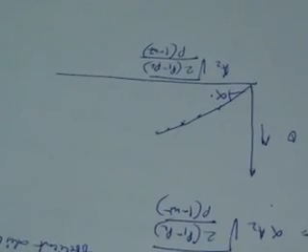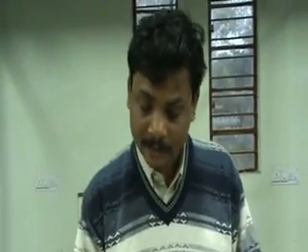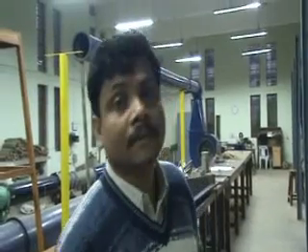Okay, so let us conduct some experiment and see how actually we can calibrate this orifice plate. Here is our setup for conducting this experiment. You can see that there is an orifice plate which is put inside the duct, and this plate is basically like a disc, and inside that disc there is an orifice. This is put into this duct, and if we want to measure the quantity flow through this duct using this plate,